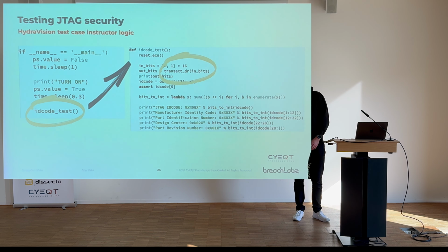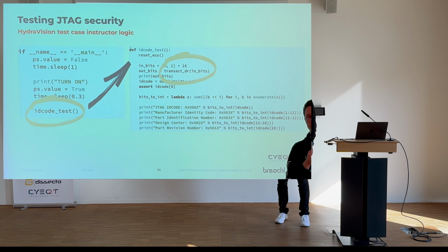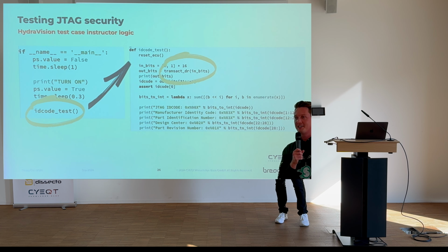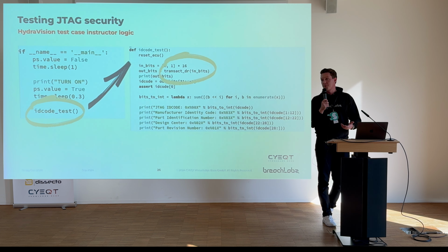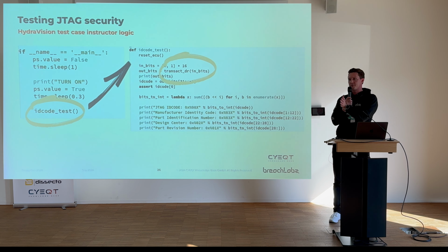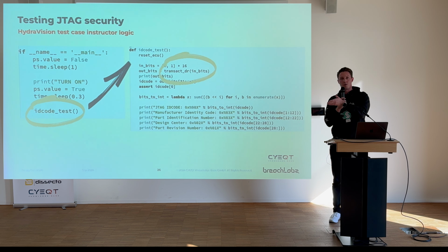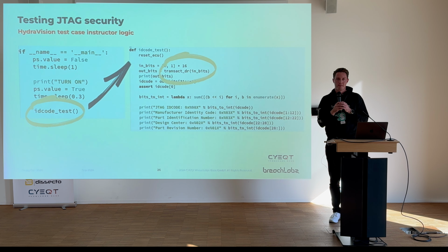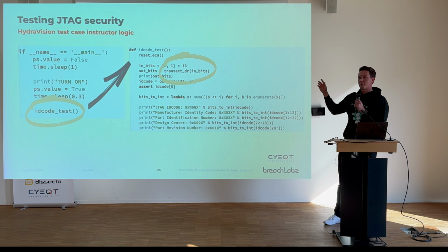Yeah. Bypass instruction and then pop through how long it is to return to itself. Yeah, pretty much, right? I mean, you can just push a lot of values into your data register and then wait and count the amount of clock cycles. Perfectly right. And how do you determine how many TAP controllers you have?